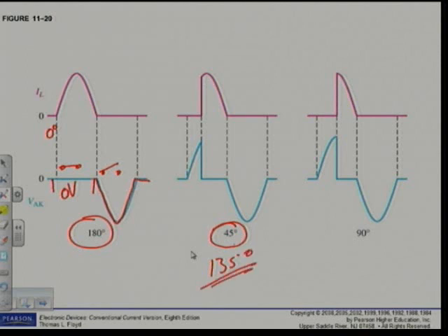That means I think the best way to rectify the problem in your books, write down, if you look at the question, relation to the load current for 180 degrees, then it shouldn't be 45 degrees. It should be 135 degrees. That means here we got conduction for 135 degrees. That means the question in the book is wrong. Change it, rectify it to 135 degrees, please. It's not 45 degrees, it's 135 degrees conduction, alright?